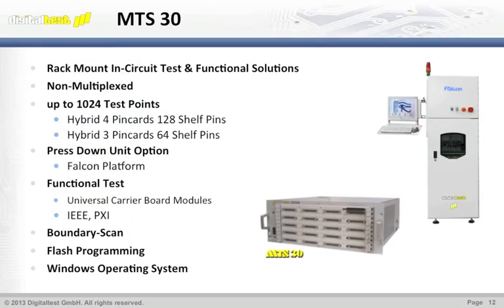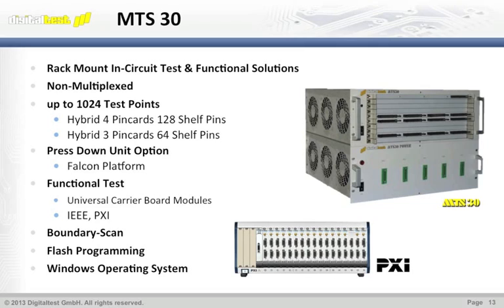If we look at our next platform, the MTS30 is a very powerful rack mount platform. So this can be customized into a solution that you need or want to go with, which can have functional test, can have flash memory programming, can have full in-circuit inside there, all put together into a rack mounted system or into any platform that you want to design together. If you put in PXI in there, we are linked with all PXI and IEEE instrumentation.